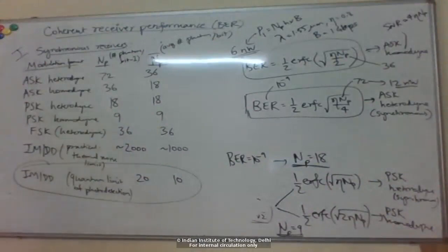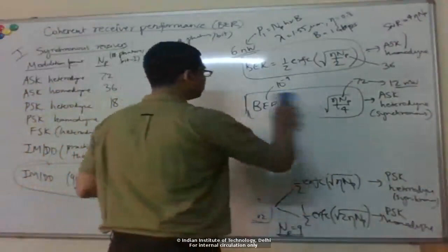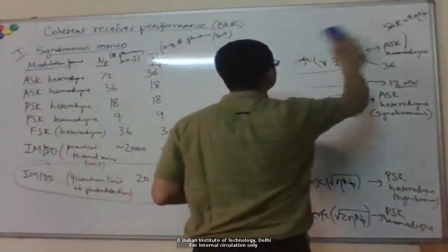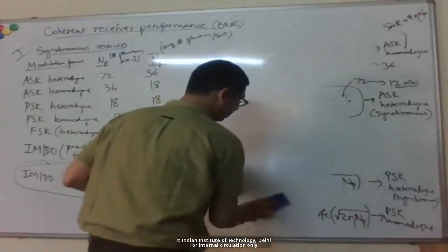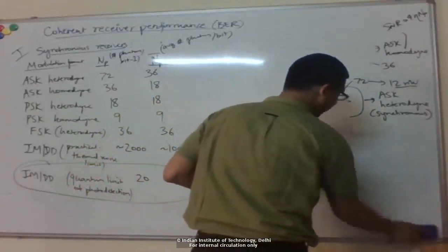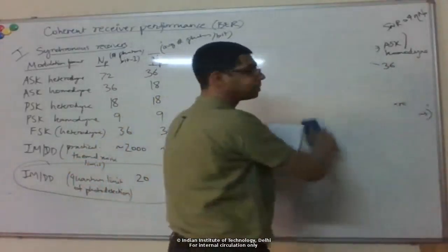Okay, so that's the case for synchronous receivers. We can do similar for asynchronous. Recall the asynchronous receiver was much simpler. We use an envelope detector, which you can typically build with a simple RC circuit, so no need to do carrier recovery using an electrical PLL or something.